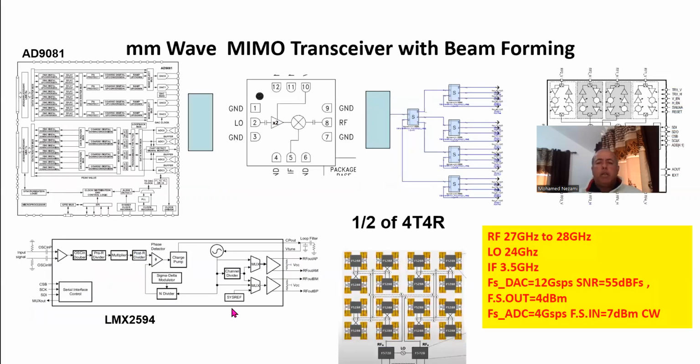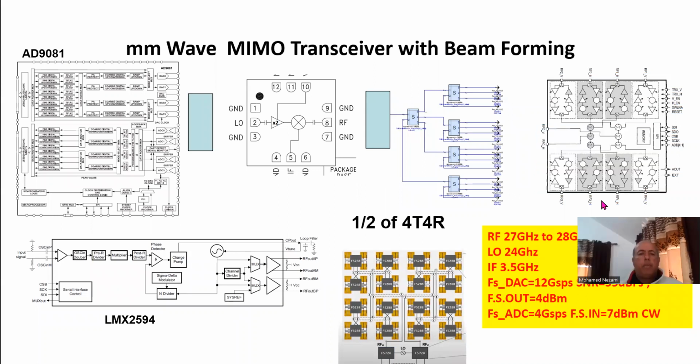So here's basically my entire hardware. I put this figure in here, which I borrowed from Renesas for the moment. We have the digital backend, and some kind of interface to the up converter and down converter, which is hit at the mixer by a second harmonically pumped LO. We've got the synthesizer in here that synthesizes the LO. We've got some kind of circuit interface to the up converter.